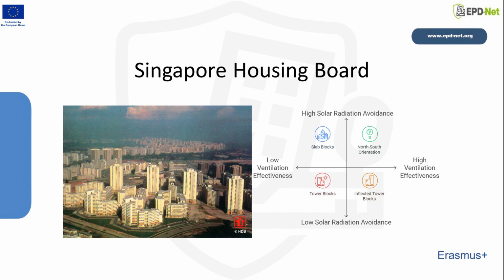Block typology. The HDB evolved its block designs, slab versus tower, to balance efficiency and environmental exposure. Slab blocks. These 12-story blocks were used to define precinct boundaries and enclosures. Their ventilation effectiveness depends on the length of wall surface in contact with the exterior, calculated per unit.